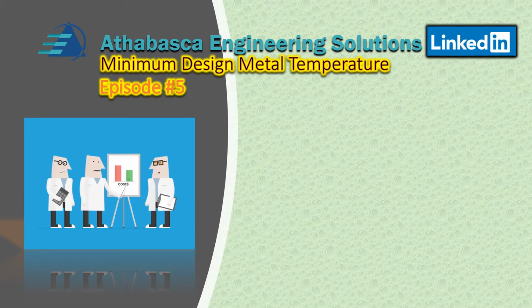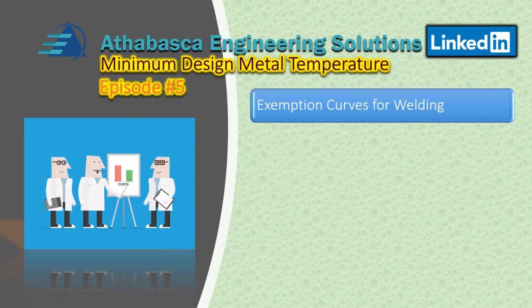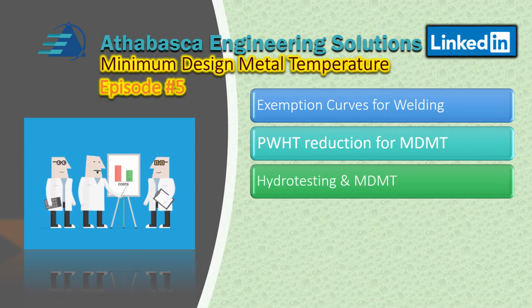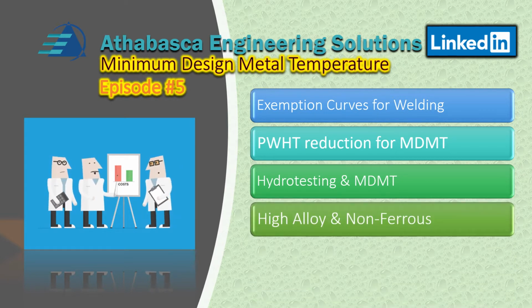Welcome back to episode 5 for the MDMT subjects, and we're at the third and final slide of our review of Section 8 Division 1. We're going to start off with the exemption curves for welding. We're going to talk about post-weld heat treatment for MDMT in more detail. And then we'll talk about hydrotesting and the MDMT. That's important as well, for safety. And finally, I'll talk about high alloy non-ferrous materials.